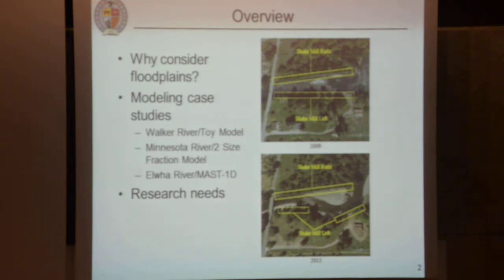Why consider floodplains? Well, I think they are an important source and sink for sediment. And I'm going to go through this using 3 case studies that incorporate both numerical modeling in a very simplified way and some field data. So all of these cases are sort of intended to illustrate why floodplains might be important. I'm not trying to show that we have the best model for representing all processes. So we'll start with the Walker River in Nevada, which was that first river that I showed on the title slide. And a really simple model, I'll call it a toy model, for how channel floodplain exchange might work.